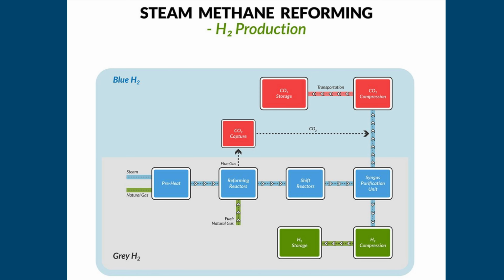Modern plants are typically integrated with hydrogen production units based on steam methane reforming, SMR, where natural gas serves both as feedstock and fuel. This integration results in significant carbon dioxide emissions, with ammonia production contributing approximately 1 to 2% of global anthropogenic CO2 emissions. The majority of these emissions originate from hydrogen generation rather than the synthesis loop itself, underscoring the importance of decarbonizing